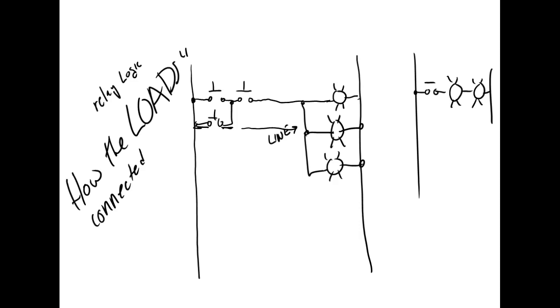Errors that were not clear until corrected. No, that's not the rule. That's the RSLogix 500 rule that runs output instructions must not be placed in series with other outputs. So there's no such thing as multi-element series circuits or multi-load series circuits in this. Now we're not teaching RSLogix 5000, so just these rules right here.